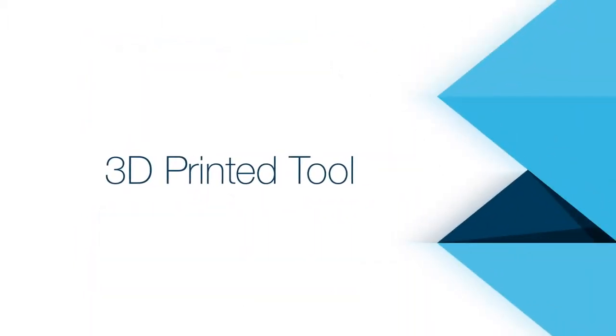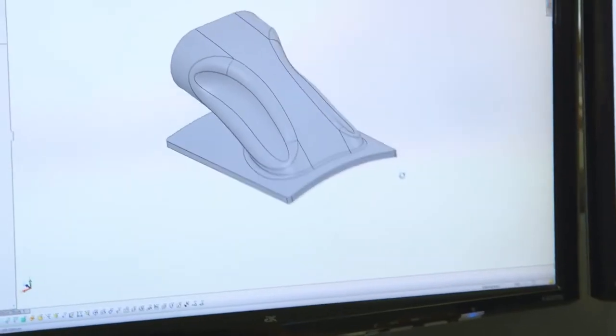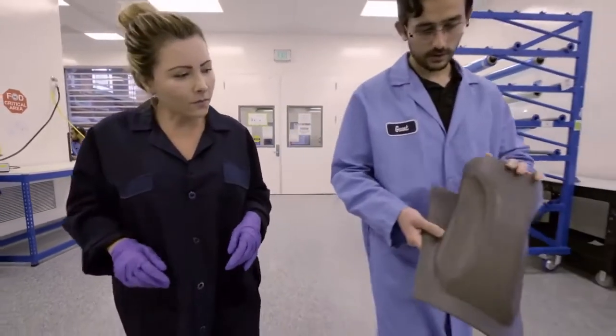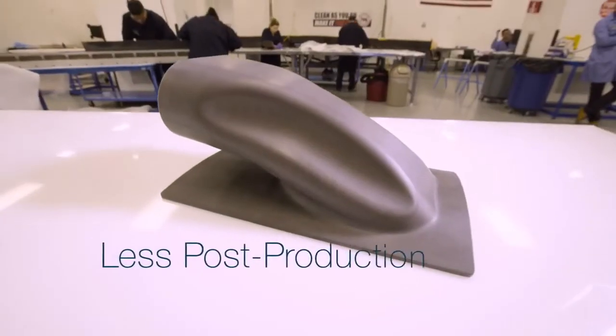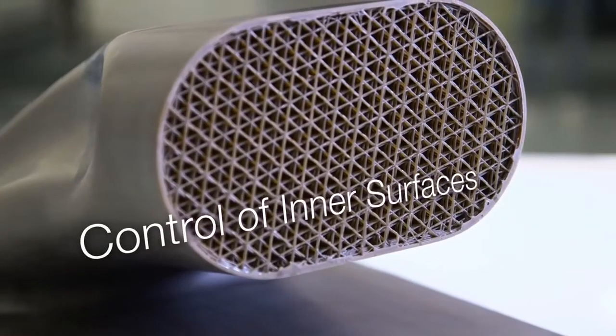The utilization of additive manufacturing in the context of composite fabrication begins with an idea which leads to a design in a CAD program. Once the design is complete, we have the tool 3D printed. Additive manufacturing allows us to have parts that have less seams, less post-production work. We're able to fabricate really complex geometries and gives us control of inner surfaces of parts that we might not have if we were using a multi-piece tool.